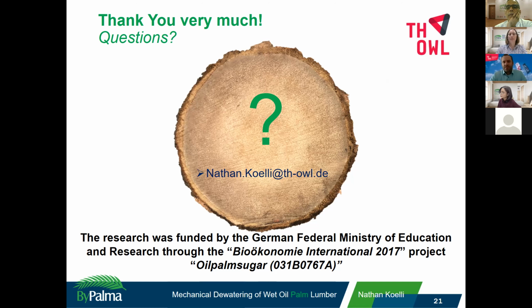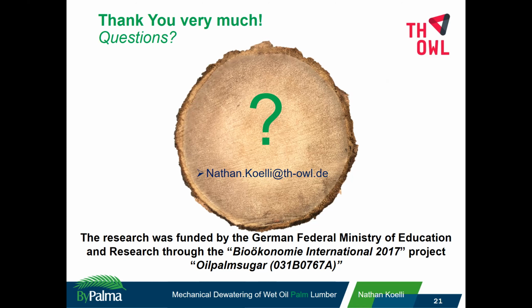We had an immediate spring back right behind the rollers to almost the initial thickness. The thickness reduction varies between 20 and 50%. But afterwards, I conducted a press drying, so then I had a fixed thickness reduction, which was also measurable. The spring back after the rollers is immediate and almost to the original thickness.